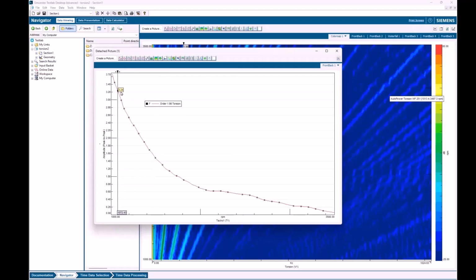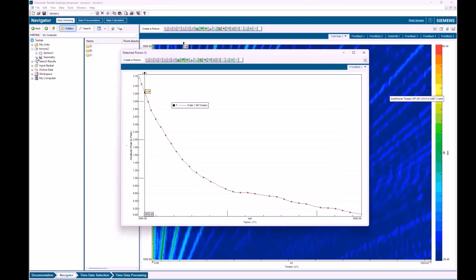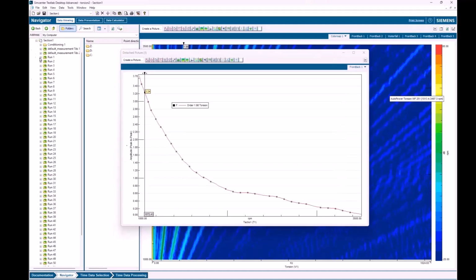That's the type of number that you might be able to use to assess the durability. Like, can my shaft withstand being twisted 3 degrees constantly? And you might even have 2 encoders and measure the difference across the shaft to see how much twist there is, right? At the beginning and at the end, in order to see what kind of deflection you have. Makes sense. That'd be interesting. So when you're doing this torsional vibration, again, you'll do a high number of pulses per rev.